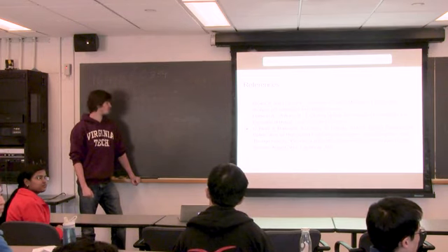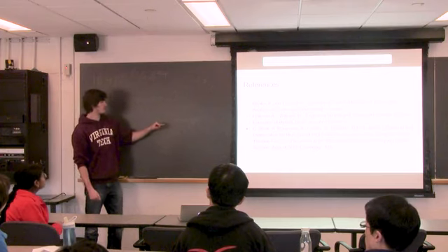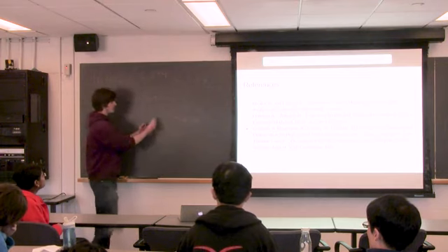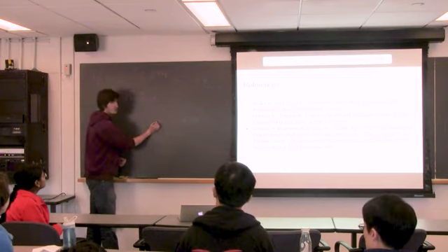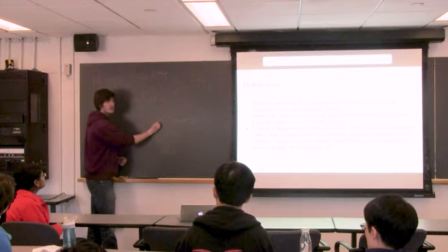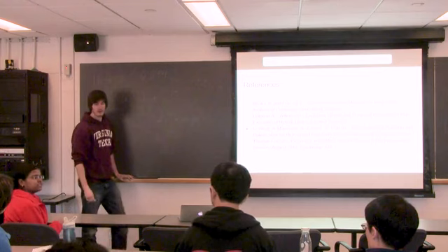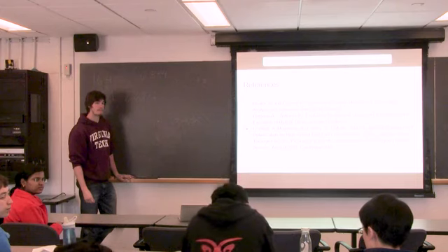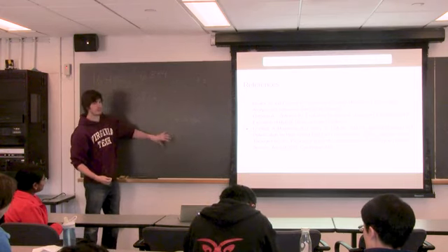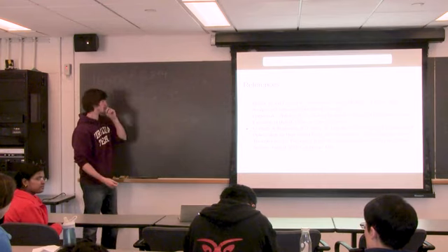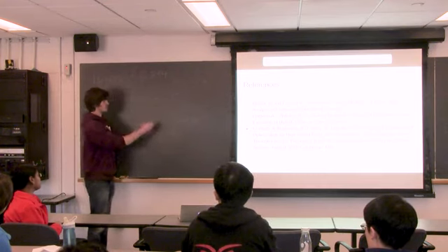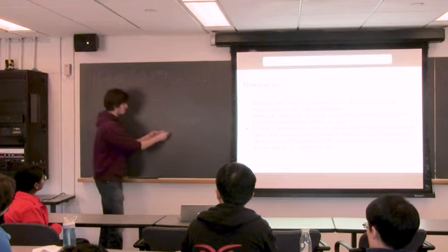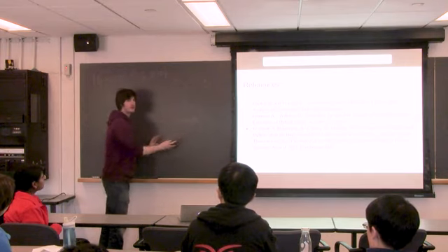Well, every time you plan a new funnel, you start at the nominal trajectory of that new funnel. So you're never going to start over here on the first one. You're always going to start at this point. But I thought the point of the funnel was so that you can reuse it without having to replan. Yeah, you can move the funnels around. Oh, you can move. Okay. Yeah. Every time you start a new funnel, you start at this nominal trajectory, but the next time you use the same funnel, you could be over here and you just shift the funnel down to exactly the same point.